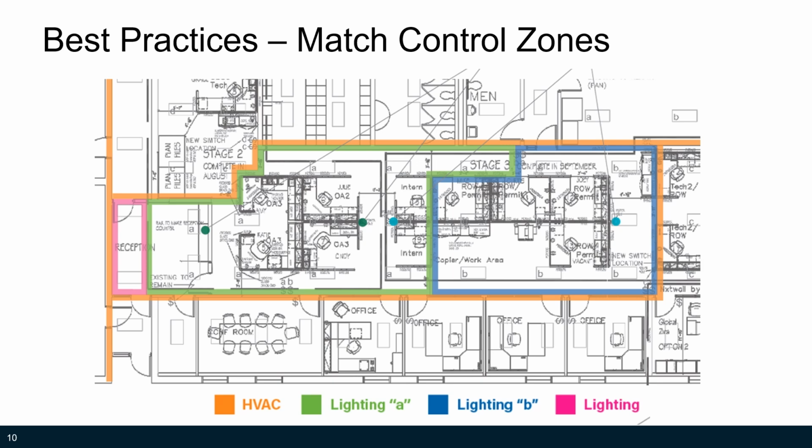In the lighting and controls design step, attention should be paid to the coordination of HVAC and lighting zones. HVAC zones are largely driven by existing HVAC system design and thermostat or terminal unit locations. Lighting control zones are based on luminaire and lighting control locations, as well as space usage needs. The coordination goal is to align lighting zones with existing HVAC control zones as best as possible.